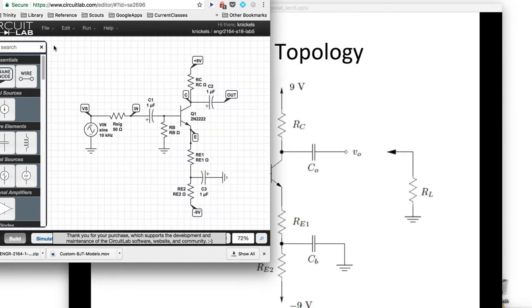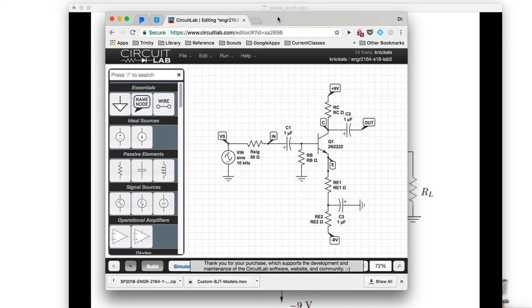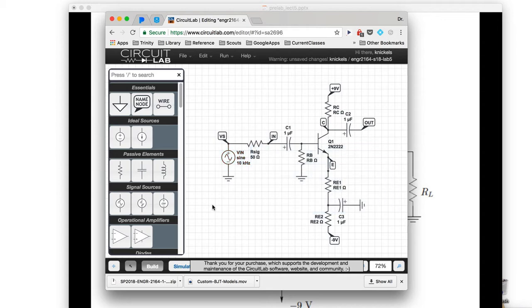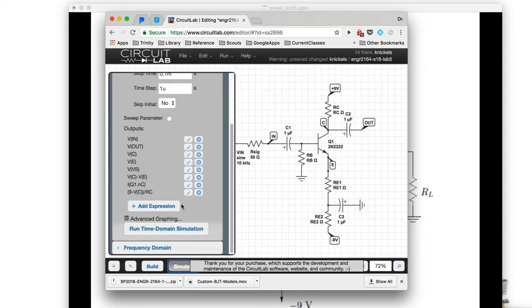That's not quite enough. Okay, so turning our attention to the specific circuit now that we have, let's see what it looks like when we simulate it. We're going to start out with a 400 millivolt input. This thing has a gain of 15 volts per volt.